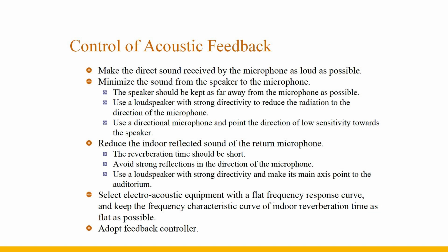The microphone of the sound reinforcement system receives three parts of sound: the direct sound, the reproduced sound from the loudspeaker, and the reflected sound of the various interfaces in the room. The reproduced sound and reflected sound are the feedback sounds of the sound reinforcement system, which increase with the increase of the amplification factor of the system. When it is large to a certain extent, it will cause self-excited oscillation of the system and make the loudspeaker whistle. The measures to control acoustic feedback mainly include the following aspects.